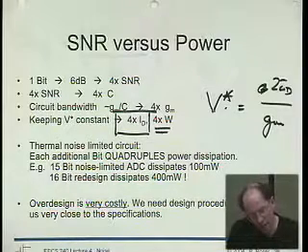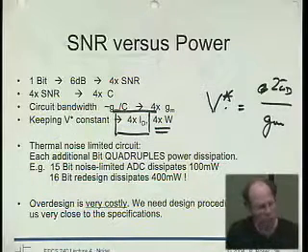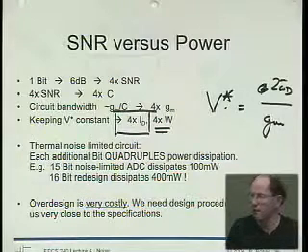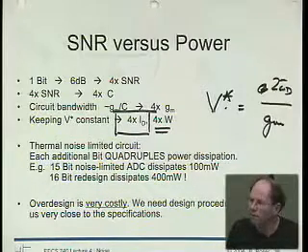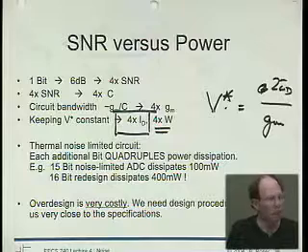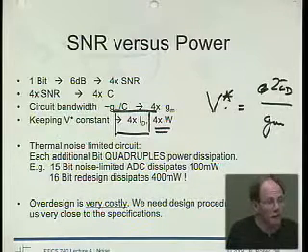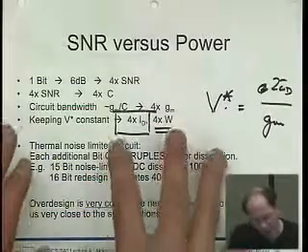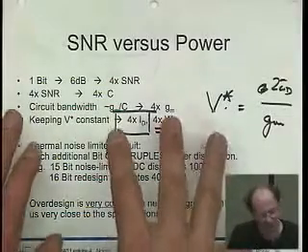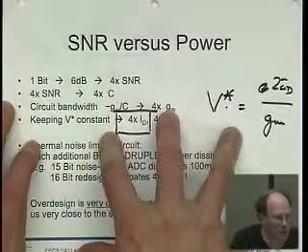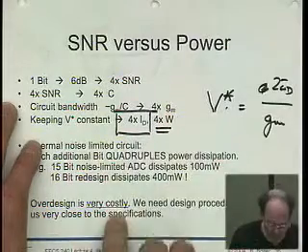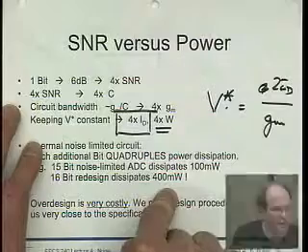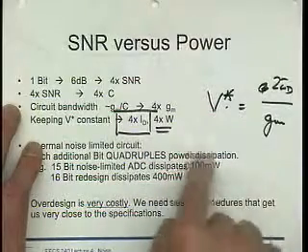And sometimes, of course, you have to make components somewhat larger to get matching. If you want 2 capacitors or 2 transistors to be ratioed exactly 1-to-1, if you make them very small, then random variations are going to make that ratio very inaccurate. So take this very seriously, but with a grain of salt. Don't already fill out your data sheet power number. You probably can do somewhat better than that because this wasn't totally noise limited.